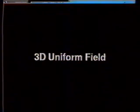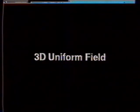Let's take a quick look at each of the AVS field types. A uniform field is a field made of uniform voxels or cells. For example, in the 3D case, each voxel is a cube. Here we see the perimeter of a uniform field. Along 2 of the faces, the edges of the voxels have been drawn as vectors. Here, a colored sphere has been placed at each voxel location. The color of the sphere indicates the value of the field at that voxel location.